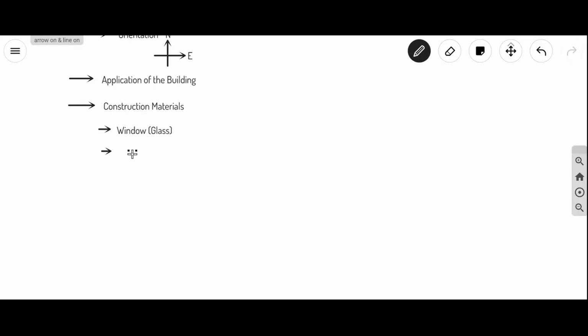Next, we need to know the material for the wall. What is the material of the walls? Partitions. So for partitions, you need to understand. Sometimes the partition material will be the same as the wall material, mostly in residential applications. But in bigger companies, the partition material differs. Somewhere they use gypsum boards, somewhere glass partitions, and recently I got one made with plywood. Different types of partition materials are used, so you need to identify the partitions.